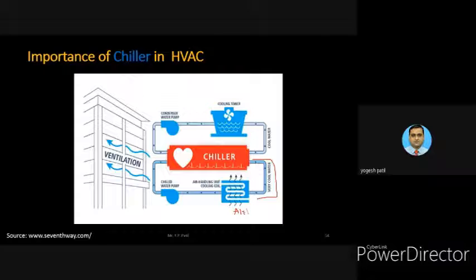This is the air handling unit, and after the air handling unit, the output is again pumped into the chiller. The chiller chills that water with the help of the upper part. In the upper part, it can be seen that the hot water enters the cooling tower. The cooling tower cools that water, and it enters the condenser unit over here in the chiller. There are four blocks through pumps.